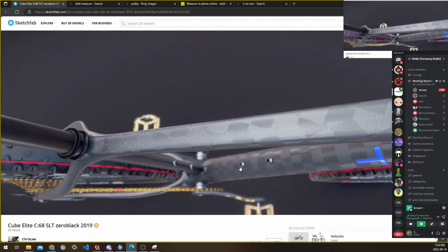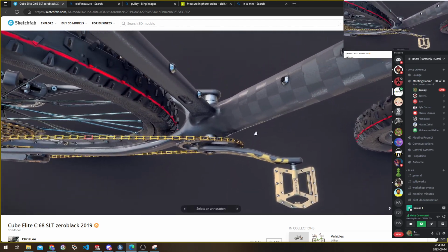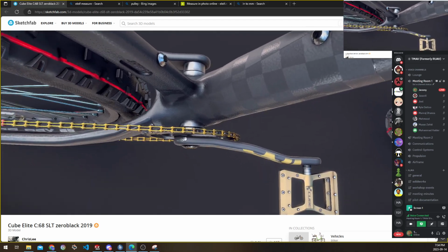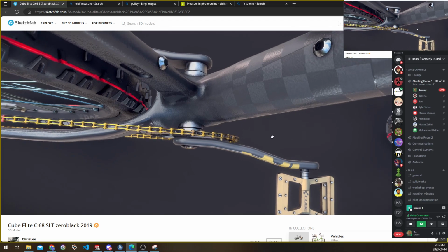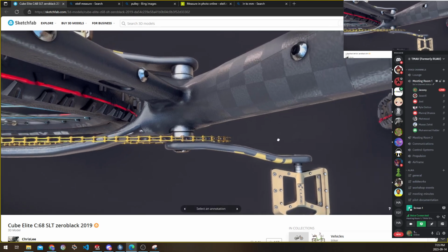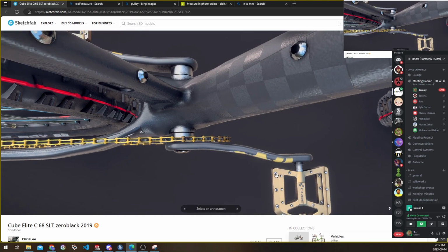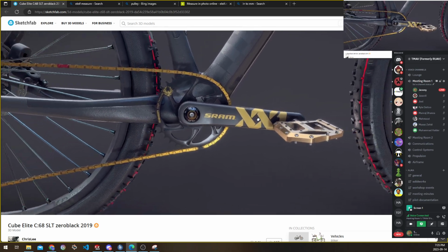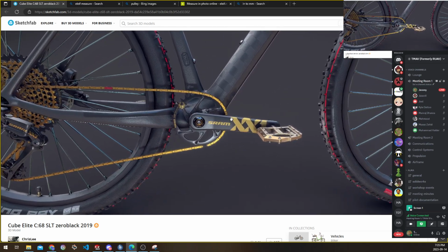And the second one is the top view, right? We know the top view is valid because it gives us a lot more information on the general overall shape. So what I will say is either one is doable, but I would say that this being your front view would be easier to cut out first. But from a part perspective, this is probably the more accurate front view. Okay, so we're going to use this as our front view.